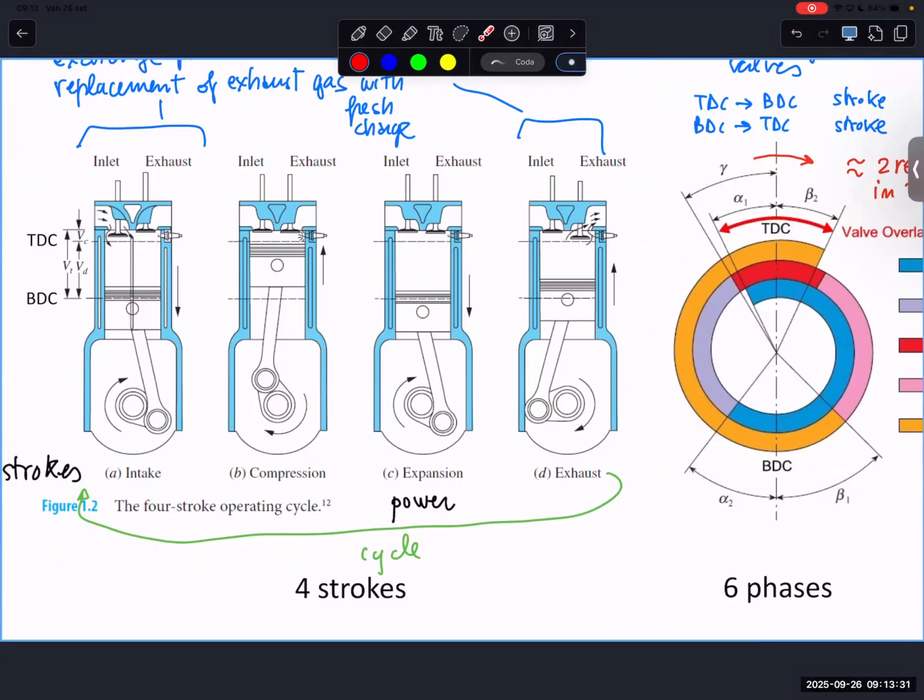But we can also provide a short motivation for this. We would like to have the intake valve already open when this phase starts. And as the opening and closure of the valve is not instantaneous, we have to open the intake valve in advance in order to have it already open when the phase starts. So here starts the stroke.